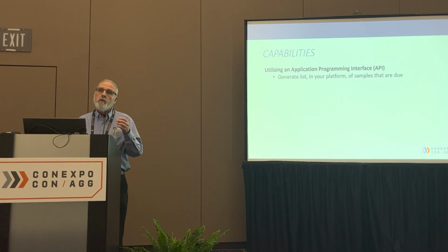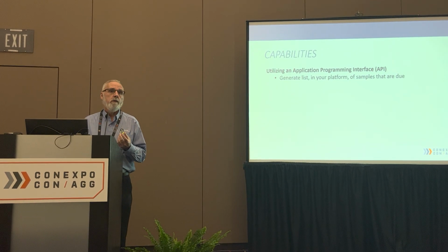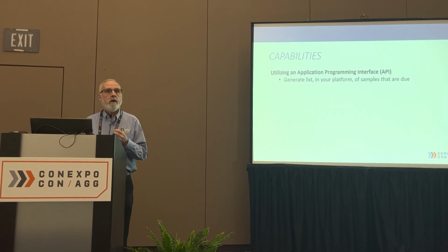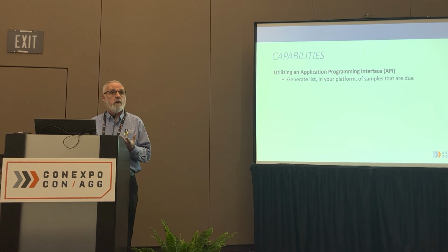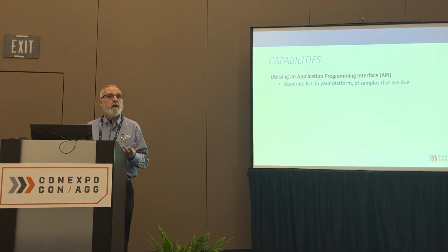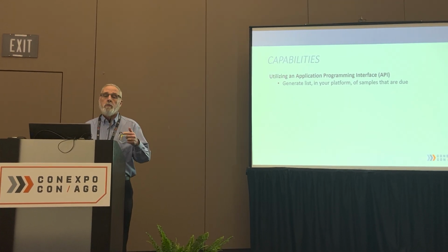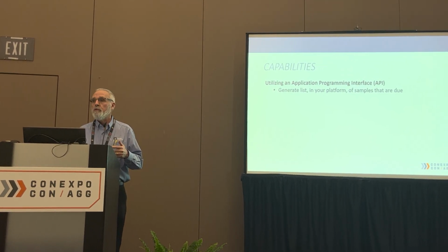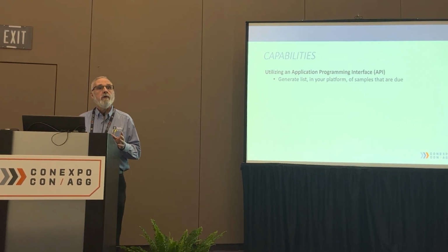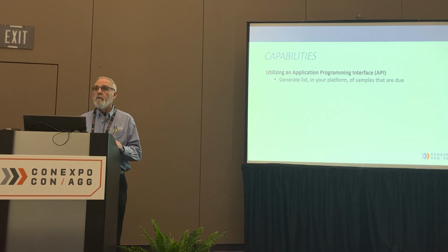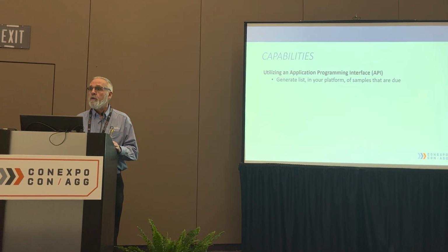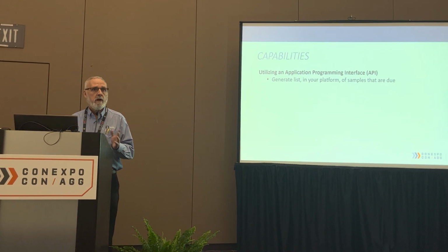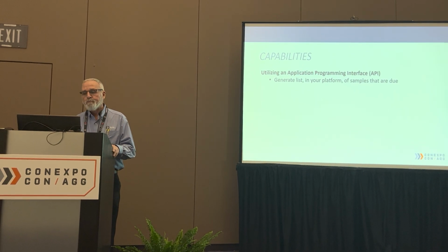So the only way to accommodate that and improve on it is to be able to feed the laboratory your real-time run hours directly from your maintenance management platform or your telematics. And if you provide the laboratory with a running tally each day of those hours, now the laboratory can tell you, you're within 10% of that 250 hours, it's time to pull a sample. And I'm going to show you some examples here of how other customers have done that.